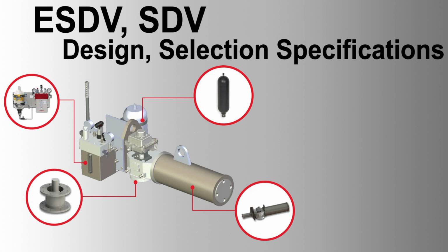Technical specification for ESDVs and SDVs. General: design life. Valves shall be designed for a 25-year lifespan. Complete assembly. The actuated on-off ESDV/BDV valves shall be supplied as complete assemblies, including the valve, actuator, and accessories. Valve type. Ball-type valves with air actuators shall be used, with trunnion-mounted or floating ball types selected based on pressure rating and size. Hand wheels, not permitted for ESDV/BDV, allowed for on-off valves.